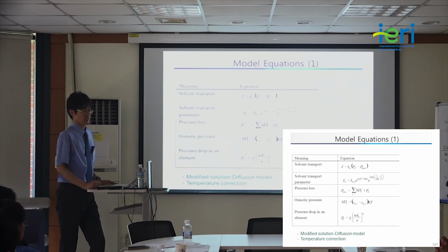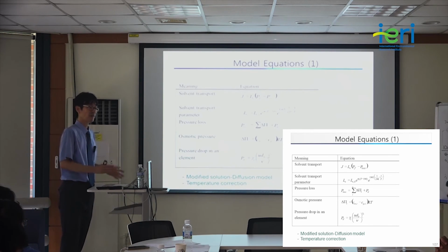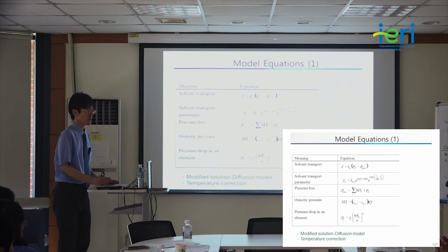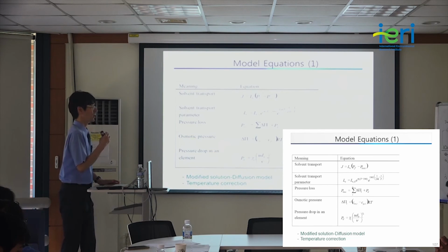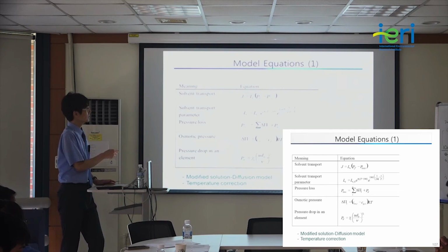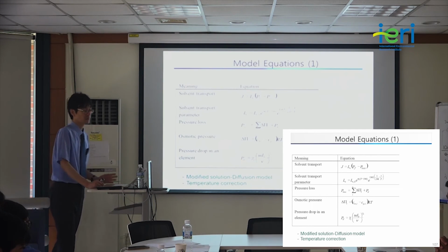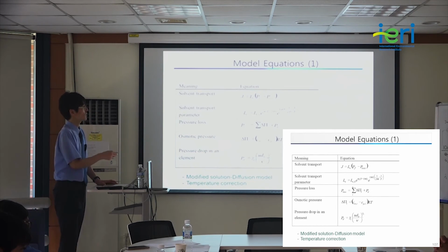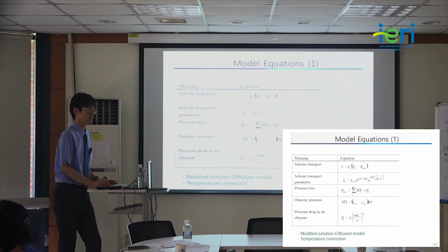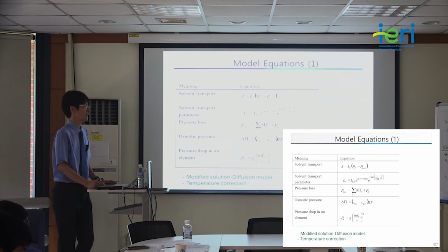The meaning of this equation is you will have a higher product water flow rate or flux if you have higher net pressure. In this case, net pressure is the difference between the applied pressure and the pressure loss terms. And this pressure loss term includes osmotic pressure and other pressure drops in the vessel or other pressure losses in a system.